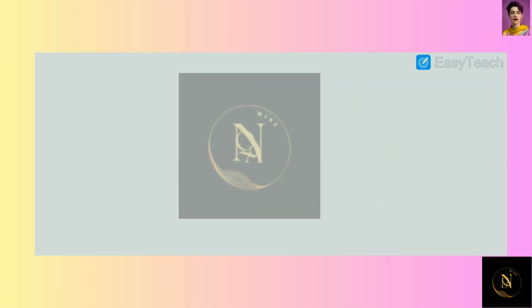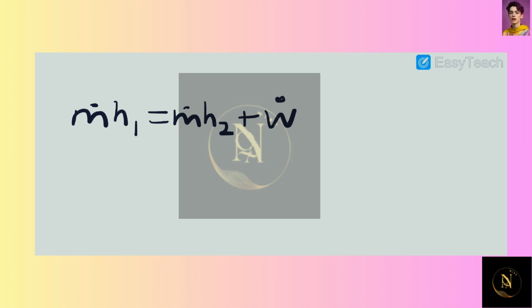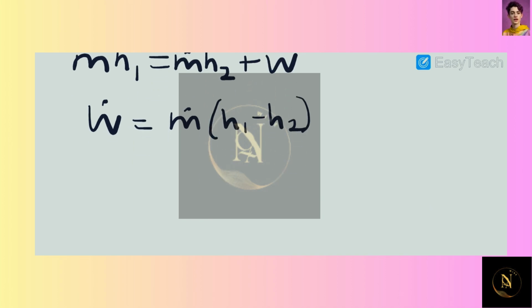So the first thing we're going to do is go ahead and do the energy balance relation for our turbine. So we know that this is going to be equal to m dot h1, which is equal to m dot h2 plus the work that is pulled out. And since the compressor and turbine are directly connected to each other, the work that's extracted from the turbine is directly transmitted into the compressor. So we can solve for the work, which gives us a power equal to m dot (h1 minus h2). And by plugging in for these values, we see that the work is equal to 1.06